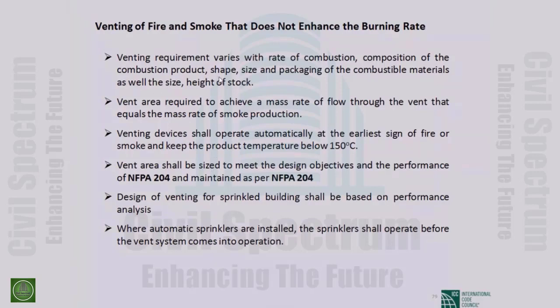Venting requirement varies with the rate of combustion, composition of the combustion product, shape, size and packaging of the combustion material, as well as the size and height of the stock. So while designing the vent, you have to consider all these. Depending on the material, it does not reach deflagration, but it is very close to deflagration. So the rate of combustion may be such that there will be a huge amount of smoke. So you have to design accordingly.